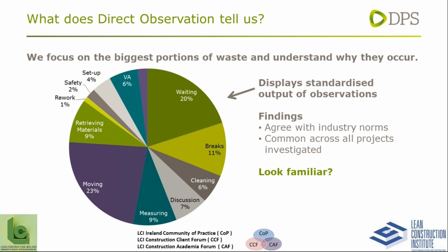Taking that to another level, we did have one particular crew unit who used BIM as a preemptive clash resolution tool. So they would go around maybe a day or two before something was going to be installed in a particular area and see where the clashes were occurring. They would take it offline, resolve the clash there and then when the guys wanted to go and build, there was no clash there for them. So that was really something that was eye-opening from a technology point of view. Yeah, that's what comes to mind anyway.